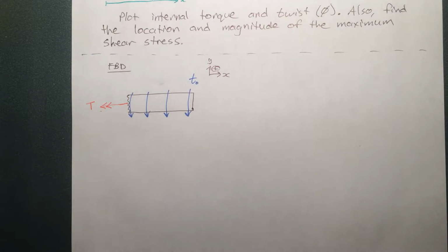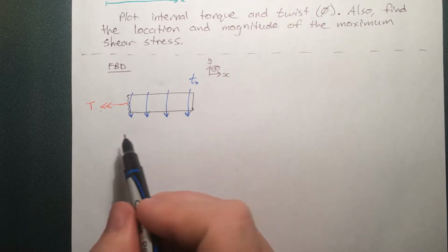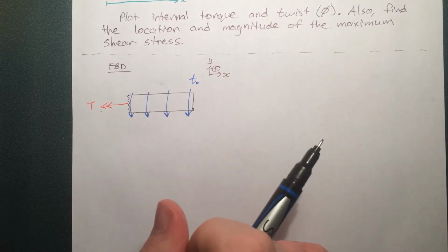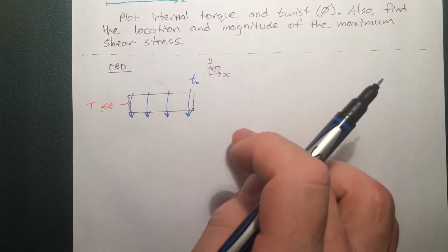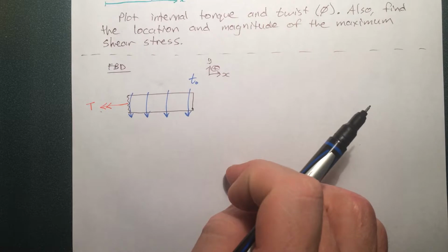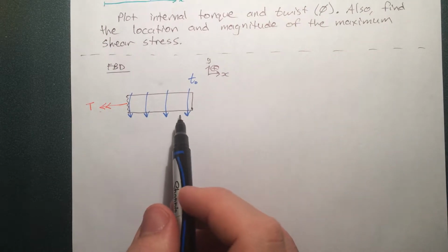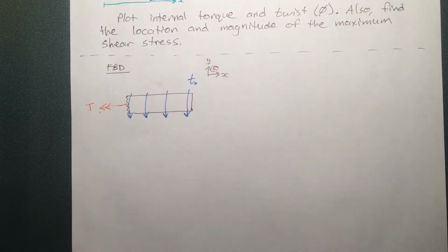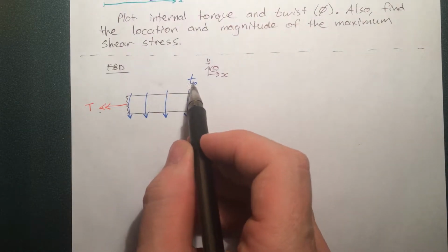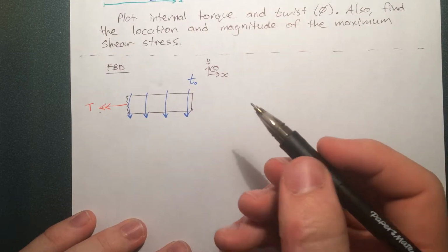We just need to replace this applied torque with a singular torque. Now we know that this is constant, so this would be a certain amount of newtons per meter, and we multiply that by a certain number of meters, that's going to give us the total number of newton meters. So it's similar to newtons per meter times meters when we had axial bars. So I'm going to redraw this free body diagram and replace it with an equivalent force. That's the result of multiplying this applied bit with this length. We'll figure out what that length is in a second.